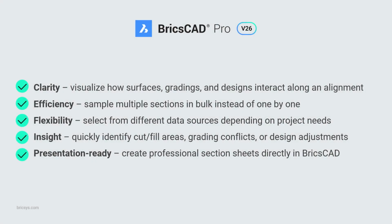So that's how easily you can create and manage civil section and section views in BricsCAD V26. We started from a surface, defined our section lines, customized the styles, and even added new entities after the sections were created, all while keeping everything dynamic and up to date. In short, you can move from analysis to documentation faster with all the clarity and accuracy you need to design confidently.